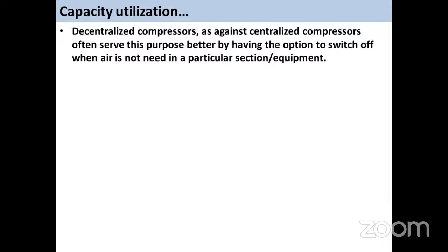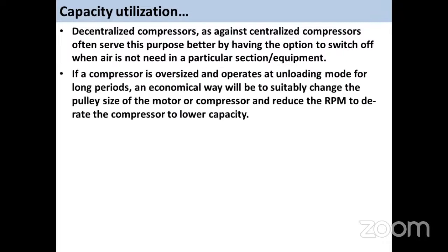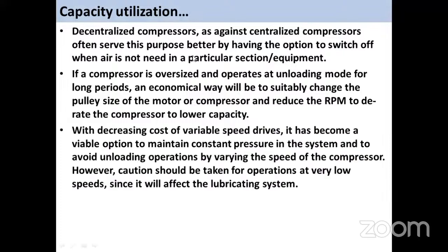Decentralized compressors against centralized compressors. You can use many systems for separate pressures and separate locations. We can use many systems instead of one common big system. If the compressor is oversized and operates in unloading mode for long periods, an economical way will be to suitably change the pulley size. This is possible to do at our end.